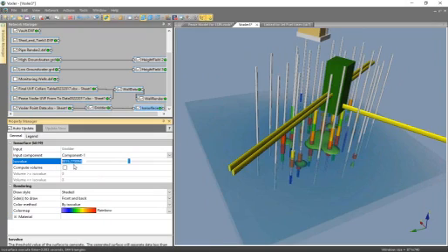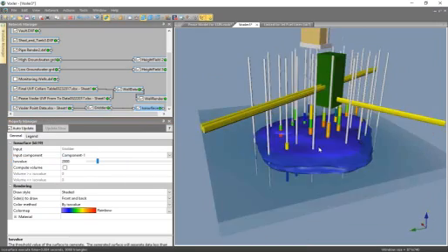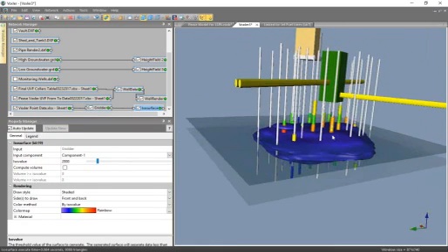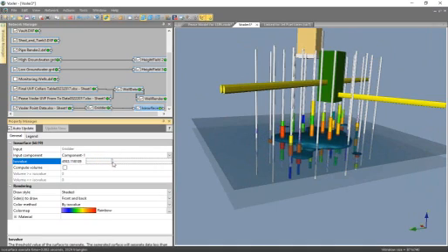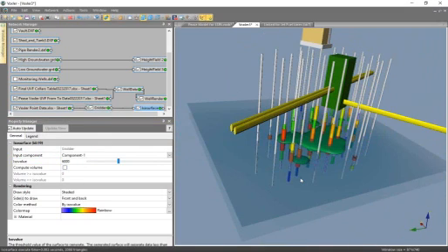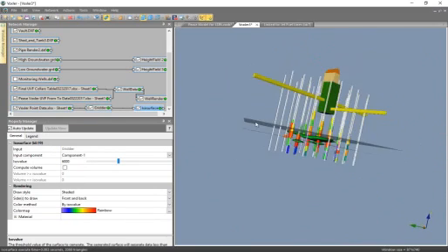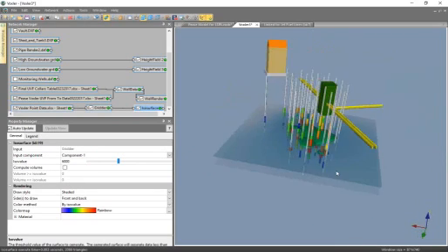And again, I know I mentioned this earlier. The target ISO values here for this data is going to be anywhere from 2,000 to upwards about 6,000, right? And you can see as I increase the ISO value here, we're going to see the concentration levels. I went a little too far there. Let me just set that to 6,000. That the concentration levels do decrease. Okay, and so now we get a really good view of the complete conceptual site model that Steve used